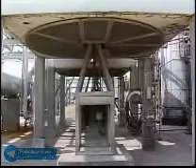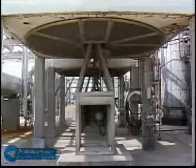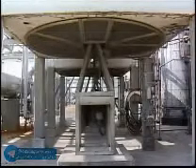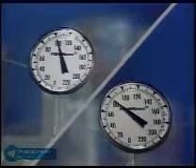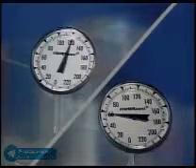The fluid transfers heat to the tubes by conduction and convection. Some of this heat is then transferred through the tubes and into the fins by conduction. From there, heat in the tubes and the fins is transferred by conduction and convection to the surrounding air. To increase the amount of heat transfer to the air, the fans in the cooler can be started. This increases the airflow through the cooler, which increases the amount of heat that is transferred by convection to the surrounding air. For example, as the difference in temperature between the two fluids in a heat exchanger increases, the amount of heat that can be transferred also increases.